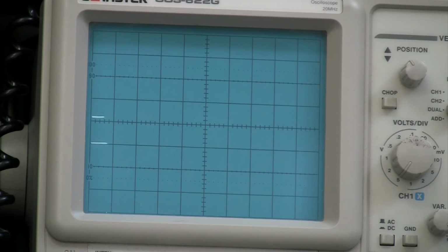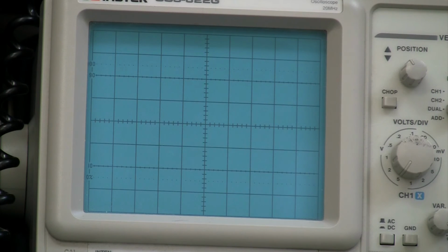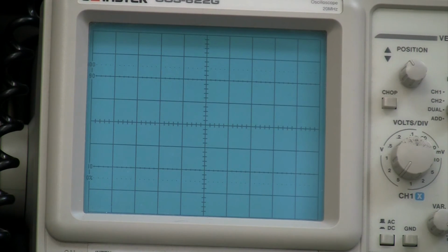All right, the last thing I wanted to show you, which was kind of the source of this video that I posted originally, was this additional segment that we can get. As we turn that control level up and the gain level up, I'll change the scale so we can see it again, at some point we're going to hit some clipping here. Now if I go over to my Q130 Clipper and I change the clipper level from its setting of 10 and turn it down, I'll turn it down to 5.